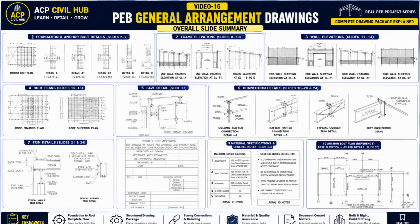After that, we explored the wall and roof systems, including wall framing, roof framing, sheeting layouts, purlins, girts, and other secondary structural members.